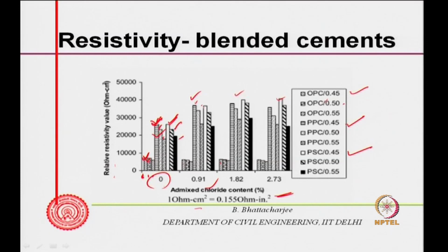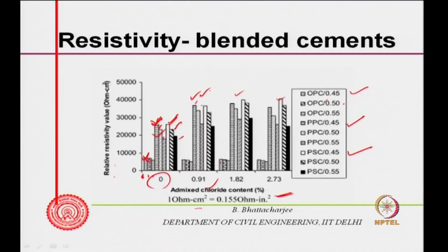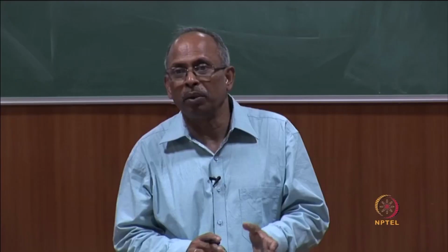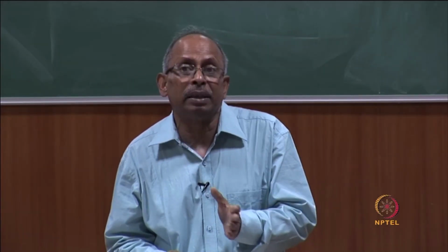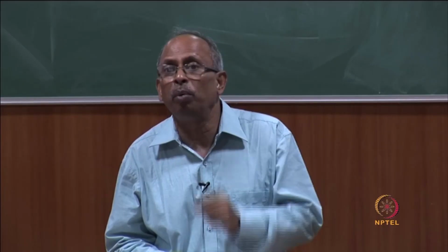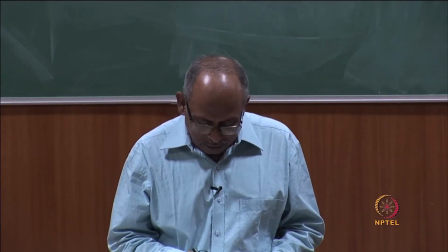Well, carbonation of course, initial phases it may not be the same, but resistivity still is better even in case of carbonation, because resistivity is independent of whether it is carbonated or uncarbonated concrete. The kinetics is controlled by resistivity, because we talked of polarization and so on. So, this finishes our discussion.